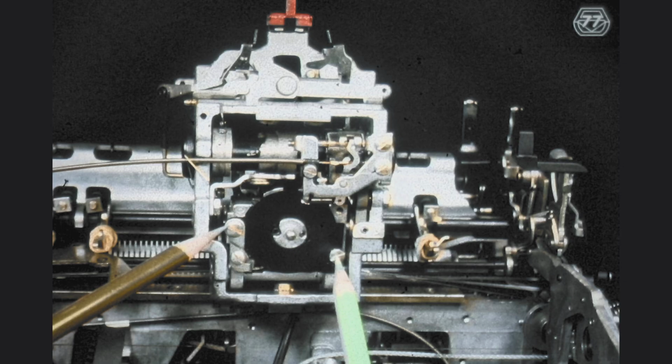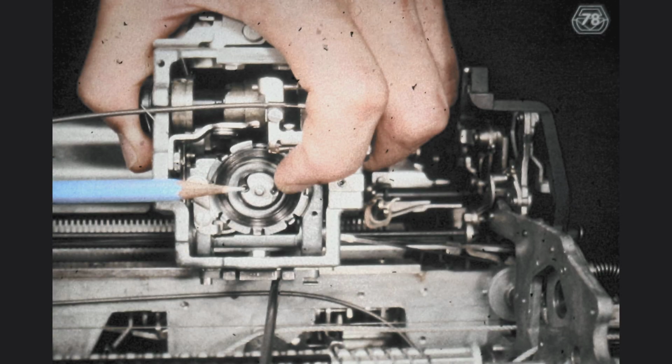You should not attempt to open the cage without first releasing all the spring tension, so let us first show you the points that are important for you to know. Later, we will ask you to disassemble these parts. While we hold the rotate spring in position to keep it from flying out of its cage, you can now see the rotate spring and the indicated point at which it is fastened to the rotate pulley. The pulley, in turn, is fastened to the rotate shaft with a set screw.